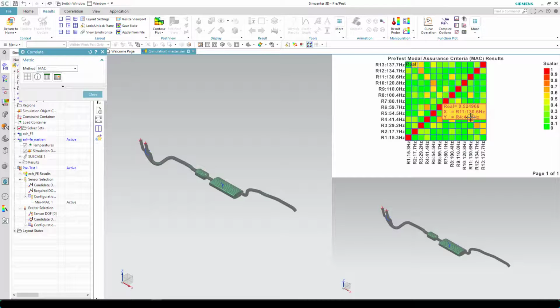Ideally, they'd be 0 or very close to 0. Yeah, like here's 0.01, so 1%. But yeah, some of these off diagonals are at 60% and they're orange. So that means the modes are 60% alike when I used 4 triaxial accelerometers.